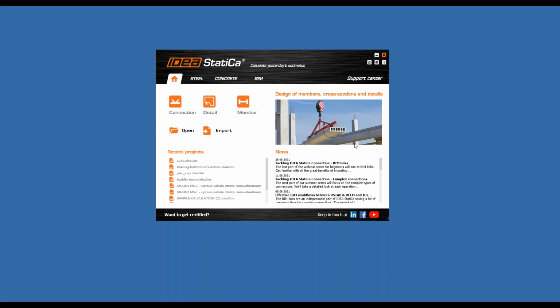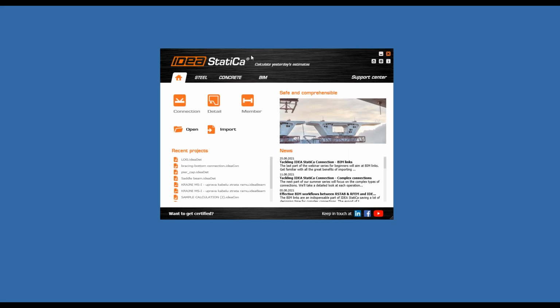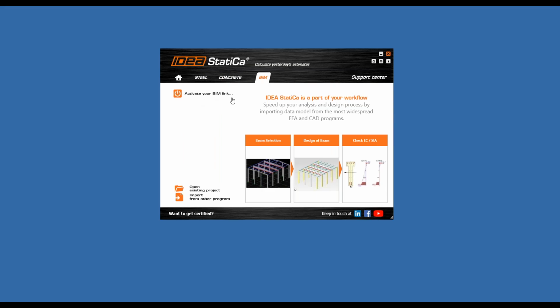So now it's time for running the BIM Link, but at first we have to install the BIM Link. So at first I run the IDEA StatiCa application, go to the chapter BIM, and here's the only one option: activate your BIM Link.